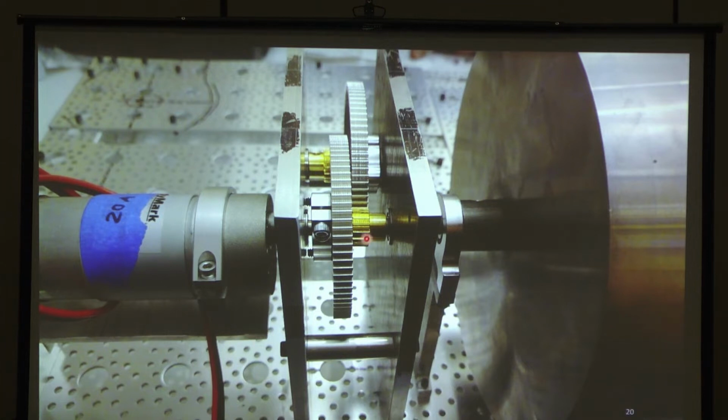We used brass pinions running on aluminum gears for lower friction, and it's better wear resistance as well. And then over here we have a jack shaft. Oh, and this gearbox is a 5-to-1 and then a 5-to-1 gearbox, so overall that's a 25-to-1. And about the plates, we clamped them together while we were drilling the holes for the bearings so that these holes line up really nicely. So they line up with a tolerance of 2 thousandths of an inch.